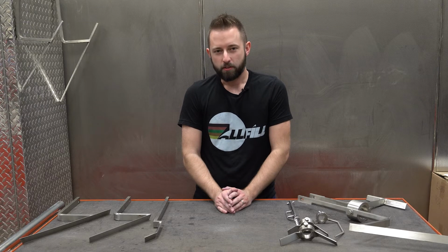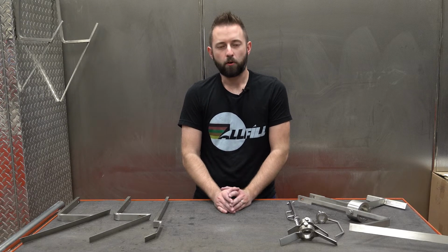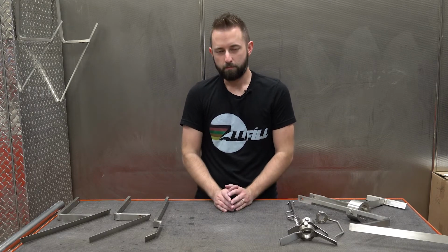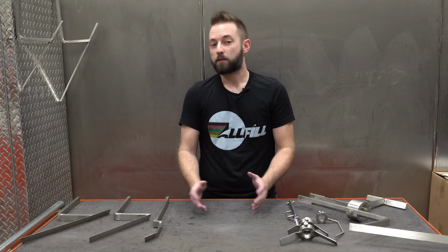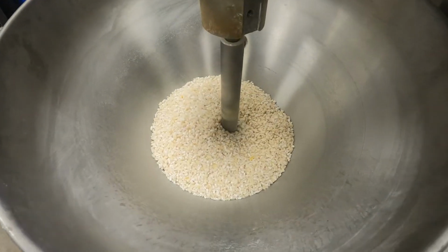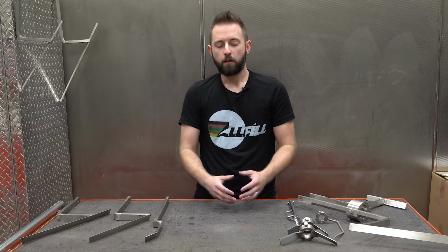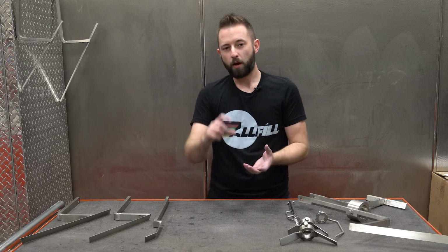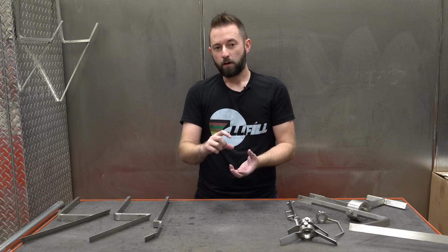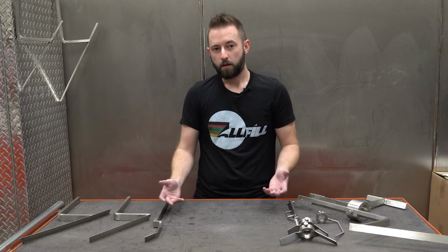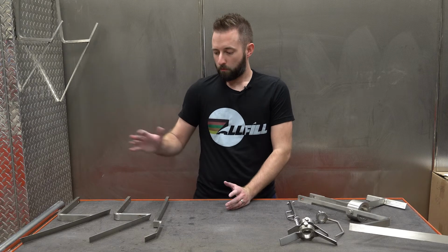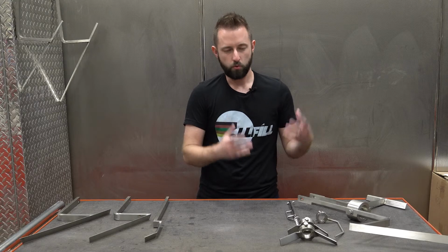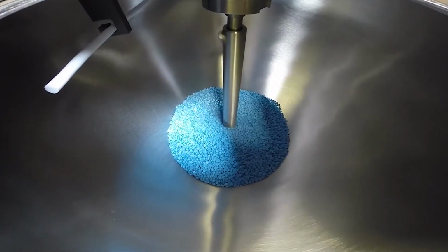So when it comes to agitation, it's a very important piece of our auger fillers in maintaining efficiency and accuracy in regards to the throughput of the machine. Without agitation, unless a product's incredibly free-flowing, we'll have issues feeding product down into the auger of the filler. Our augers rely on a consistent, uniform amount of grams per revolution, so the amount of product that's in between each flight. If that varies, that's where you start to see fluctuations in accuracy and overall performance of the machine. So these various types of agitation help with different types of products in gaining as uniform and efficient flow of product through the auger filler as possible.